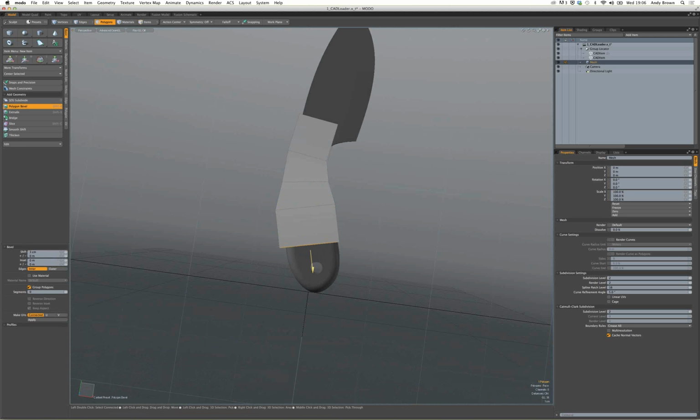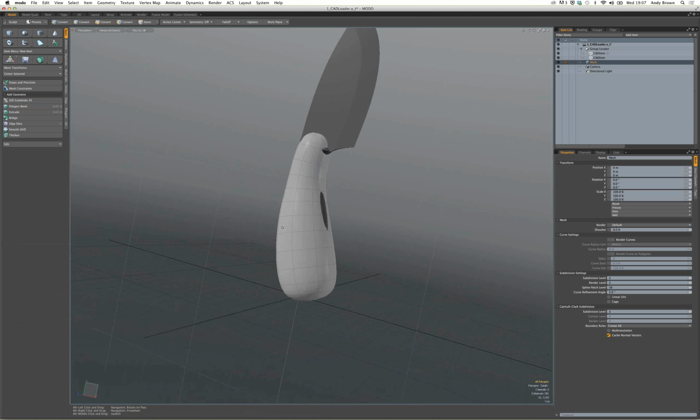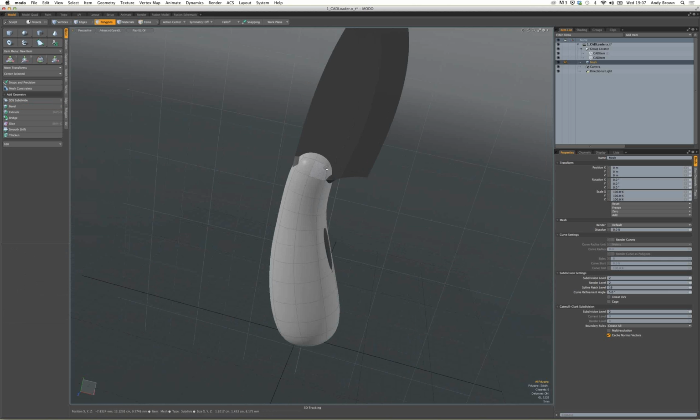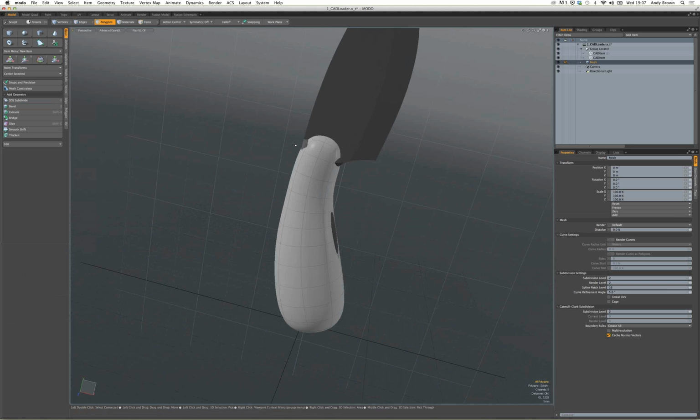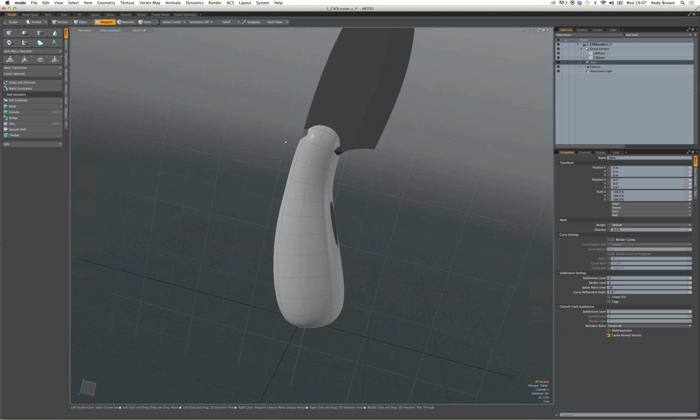Just quickly. Okay, just beveling out a little shape here. We'll just scale that in at the end. Okay. I just subdivide that with the D key and then hit the Tab key to create the subdivision surface. So MODO at its heart has always been a fantastic subdivision surface modeler. And subdivision surfaces allow you to create very organic shapes very, very easily. It allows you to play around with those shapes very easily using fall-offs and a variety of editing tools. So it's a very different way of working than working with NURBS. So you're not starting with a curve and then building from that. You're starting with volumes and then you're pushing and pulling those volumes around.